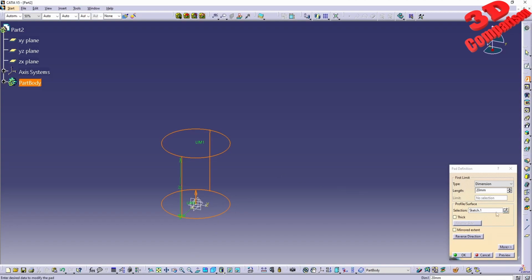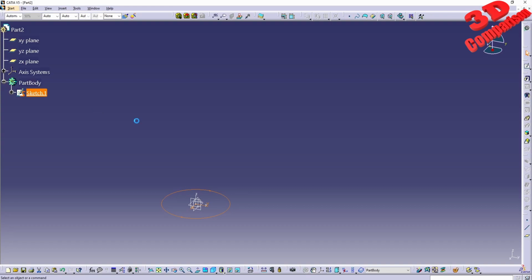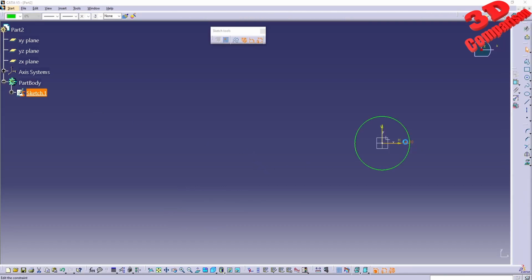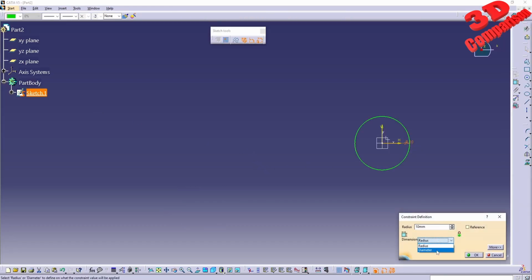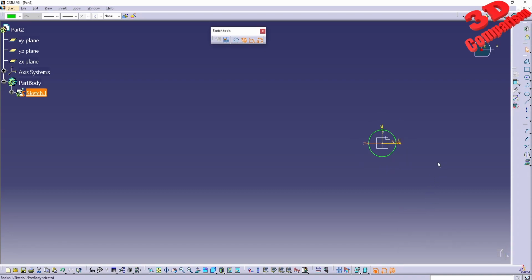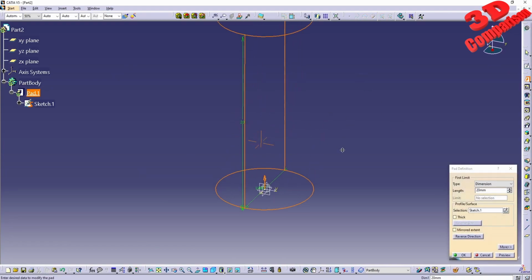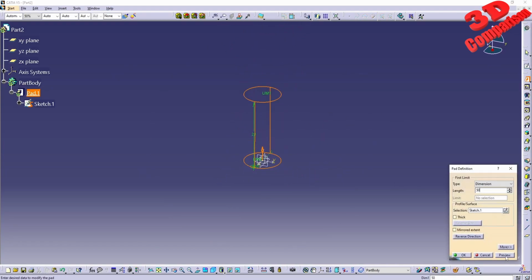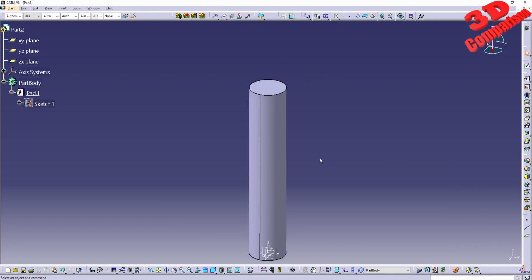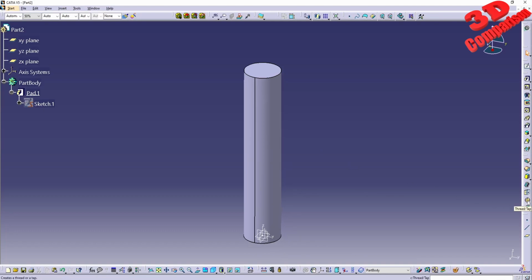So this is why we're gonna change that. We can double click on this. Since this is set by default to radius, I will just change it to diameter and only have it to 10, since we want to define a metric 10. So we have that. Afterwards, I'm gonna go with an extrusion. I'm gonna make the base 50 millimeters.